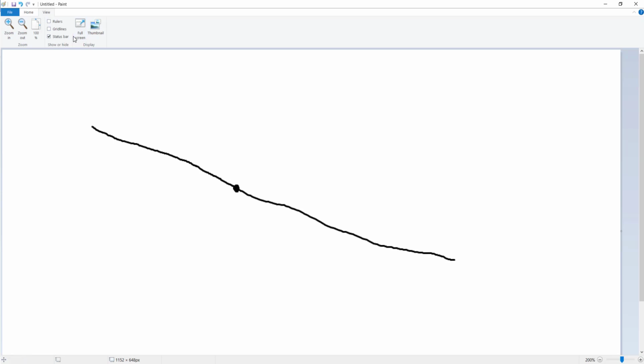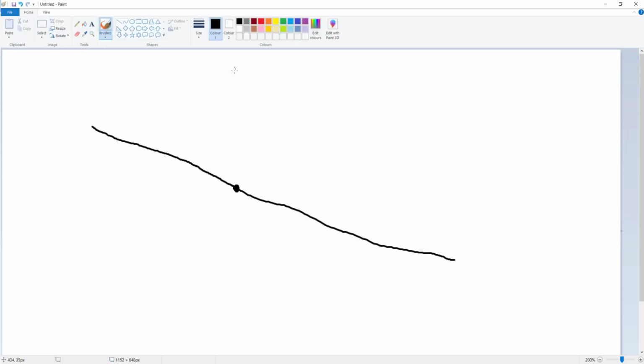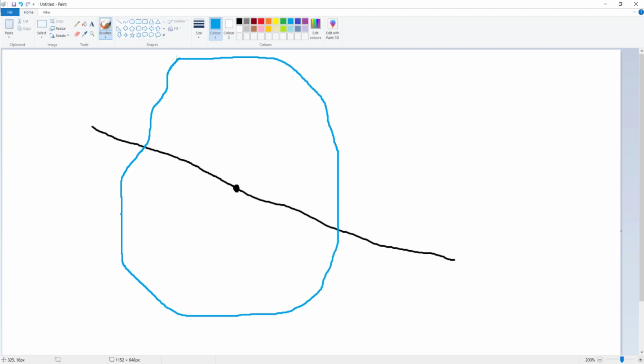Now, as I said, our next job, using our skill and judgment as hydraulic modelers, was to estimate what area would actually drain to that manhole. Okay, so that's our area. And my assessment is that this area will drain to this manhole. Now within that area, there's going to be a land usage. And remember, we are designing typically new housing developments, industrial estates, commercial developments, that sort of thing. But let's say this is a fairly typical urban area.